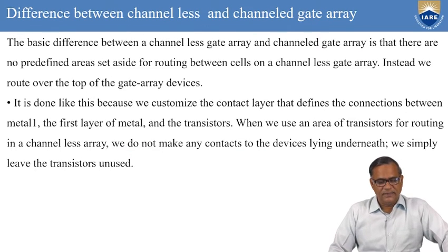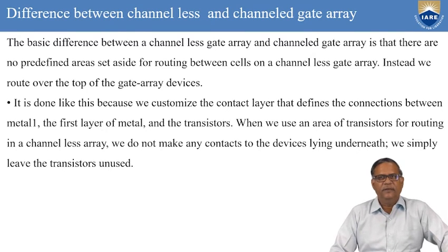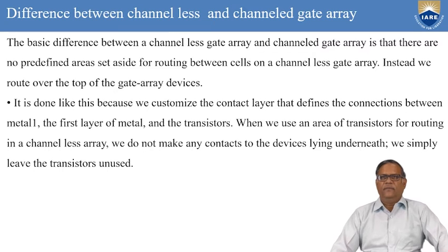Now again, let us discuss the differences between channelless and channeled gate array. The basic difference is that in channelless gate array, there are no predefined areas set aside for routing, but in channeled gate array, we have areas which are set aside for interconnect, and that area has a fixed height.